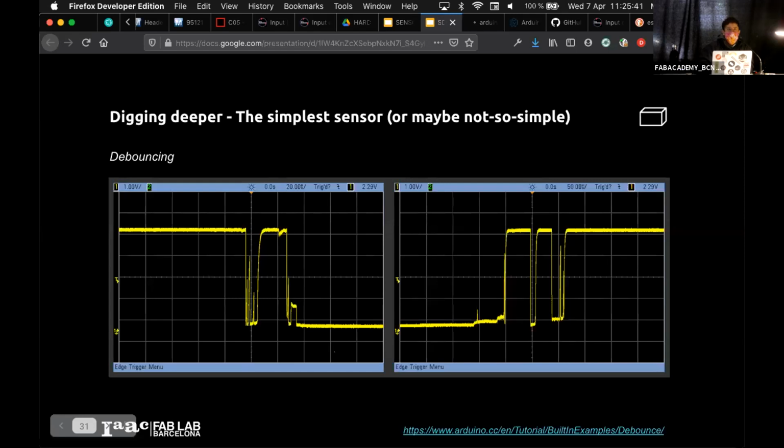And we only assert that we are stable once we've been stable for a certain amount of time. Say, if I am reading here and I read again and again and I am oscillating, I don't say I am down. I only say that I'm down once I read 10 times that I am on the lower level. Okay?